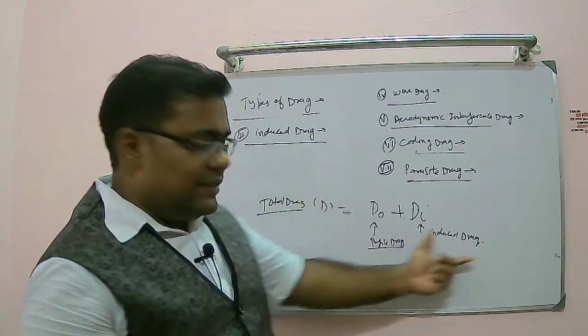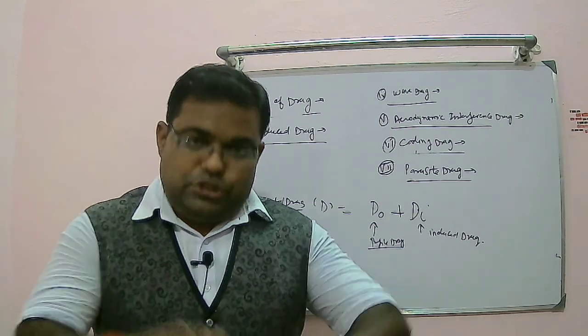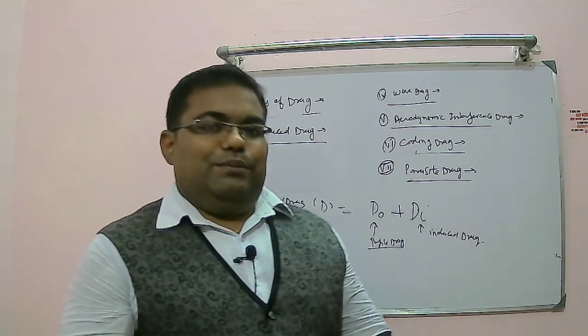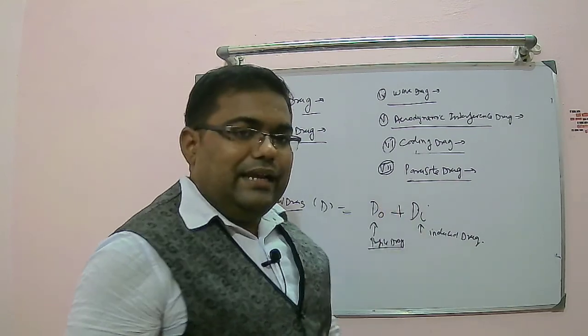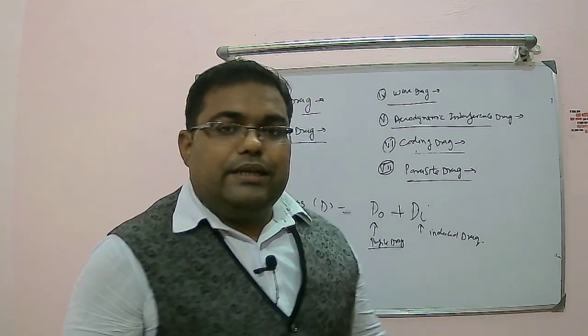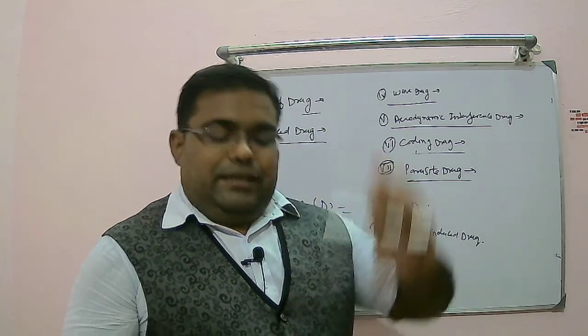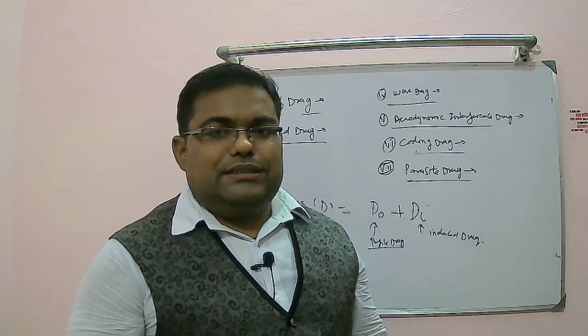If you look at the contribution, this profile drag contributes 15% of the drag. Usually when we do the calculation, you will come to know. So a 15% contribution in total drag is due to the profile drag, and the rest, 85%, is due to the induced drag. That's why we say avoid the trailing edge vortices, make some arrangement to avoid them.